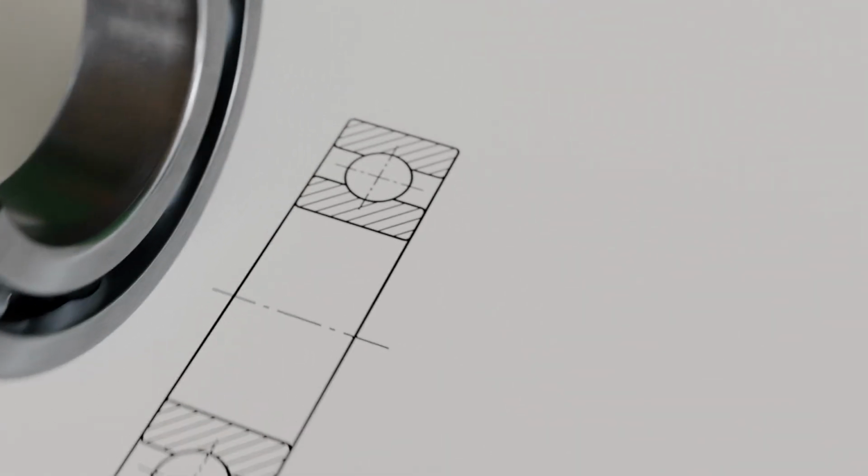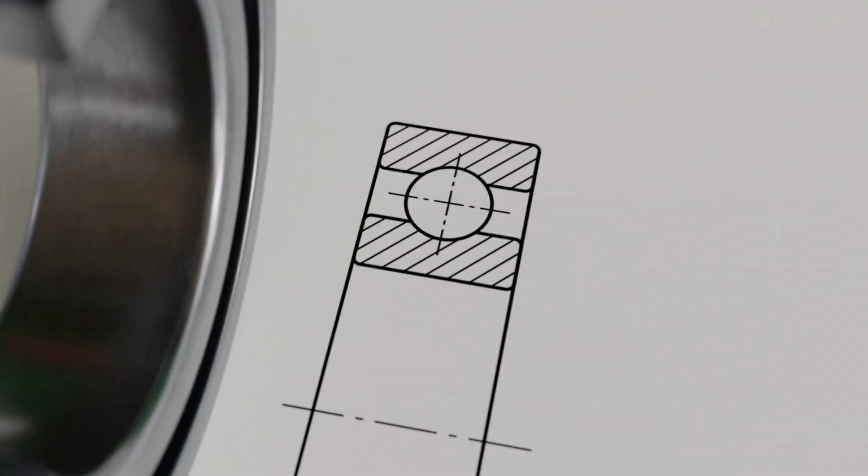In technical drawings, ball bearings are usually shown in full section, with the rolling elements not cut through. Since a rolling bearing is a pre-assembled integrated unit, the inner and outer rings are given the same hatching to indicate their association. For reasons of clarity, the cage is usually not shown.